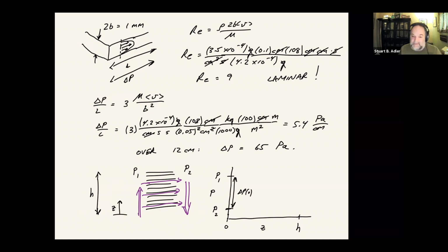But what's going to happen as this gas is going up the channel, that's also subject to the same laws of fluid mechanics. Again, if we're talking about laminar flow, pressure drop is proportional to the flow. The flow is maximum at the bottom because we're putting in all the air at the bottom, and then it's maximum on the exhaust side too, because it's maximum downward at exhaust. And so that pressure drop per unit height is going to be greatest right at the bottom, and it's going to drop off kind of like that.